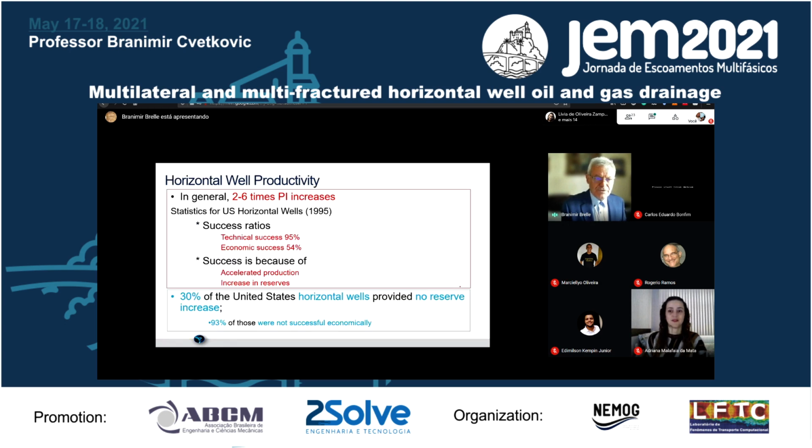Okay, so you see, in general, when we talk about a horizontal well compared to a vertical well, we can increase the productivity index, which we know is Q divided by delta P. We also know that that is the Q. The delta P is really your P reservoir minus bottom hole pressure, BHP.